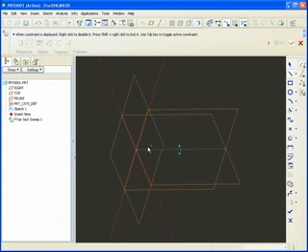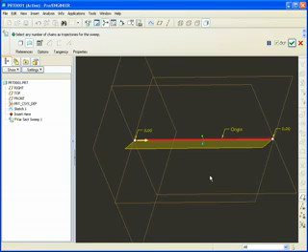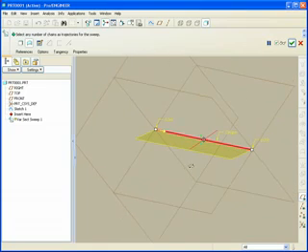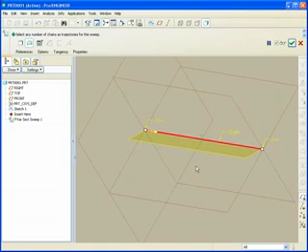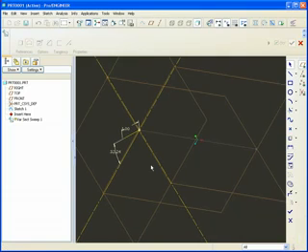I'm going to make a line emanating from that center, dimensioning it such that I can control its length as well as an angle. Now the length of the line will ultimately be the radius, and the angle will be how this line spins. Well, let's take a look at that. If I don't do anything to it, this variable section sweep will yield essentially a planar face. Let's go back to the sketch. Now what I want to do is vary this angle.